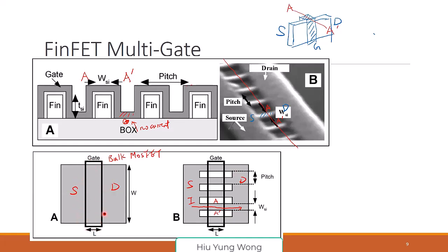We're looking from the top. Okay, this is the bird view. If I look from the top view, just like a bulb, you start from the top, and then it is off. And then now you turn it on, apply a gate bias, then your current can go on. Same for here. When you have a gate that is negative bias, all these fins are turned off, no electron. So current cannot go through. You apply a high gate bias, then the channel is formed inside this fin, then they can go through. Do I answer your question?